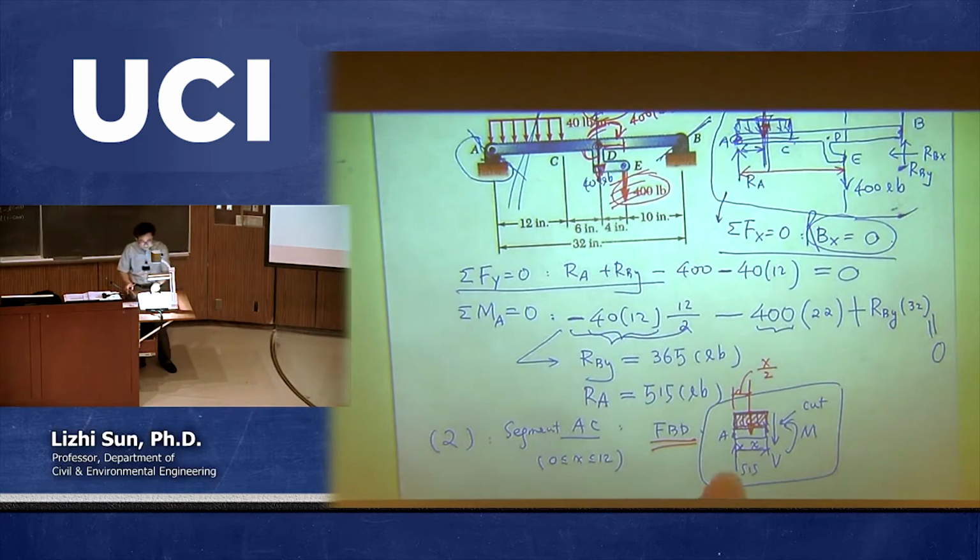So if you want to later write down those 2 or 3 Newton's equations, you need to make such equivalence between the uniform distributed load and the concentrated load. But this should not happen in the first place when you talk about the entire structure before you make the cut. So you have to make the cut, plot the free body diagram, and then you are ready to transfer from the uniform distributed load to the equivalent concentrated load.